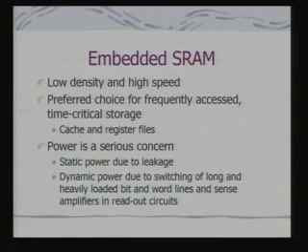Now, we also have seen that we have SRAM which is already embedded inside a microcontroller chip, and when such an SRAM gets embedded into a microcontroller chip, basically the designer has taken care of all these timing requirements. So, you have got a compatible memory on chip. Externally, when you are interfacing, your selection of memory block has to depend on these parameters, and that will also dictate the speed at which external transactions can take place.